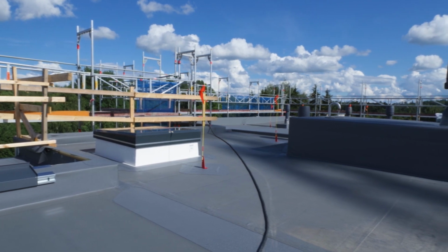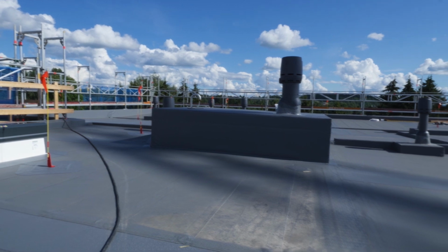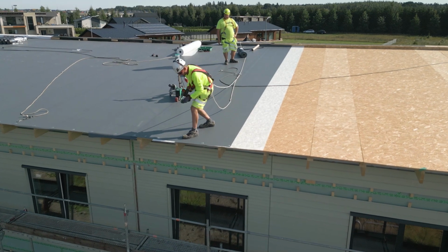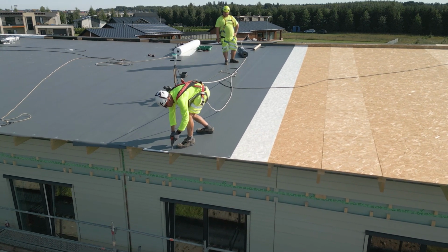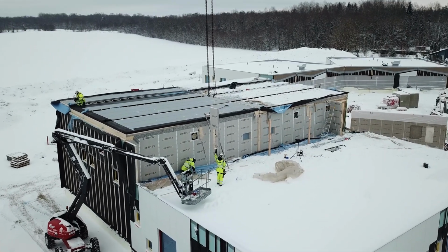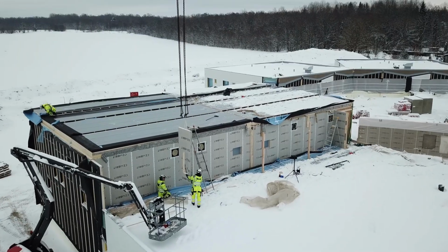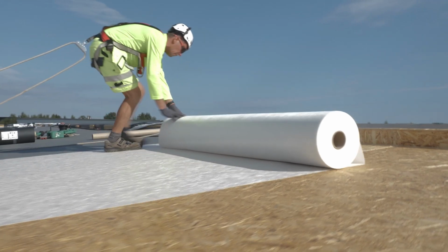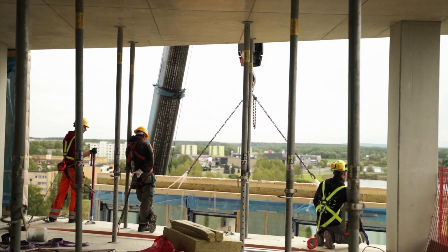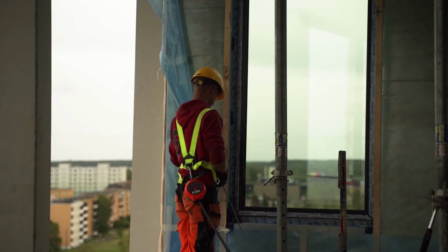When working on a roof, there is a risk of falling from a height, which requires safety measures to be implemented for falls from over 2 meters, such as guardrails, safety nets, and similar protective equipment. The risk of falling is greatest during the winter months when the roof surface may be icy and very slippery. If the nature of the work makes their use impossible, the worker must be provided with a safety belt or harness and secured with safety lines, or use other securing methods.